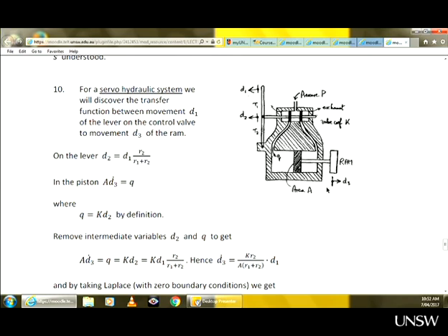If we agree that this is an integrator, now you need a feedback loop. You need to measure this displacement and adjust the displacement of this lever. That would be a kind of feedback loop. And then you apply a ramp, then you are pushing continuously without stopping. So we are talking about steady-state error over a closed loop system. It's not just the error of this, but you have this inside the negative feedback loop.